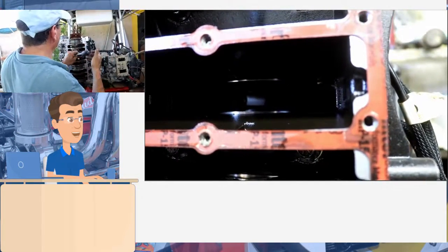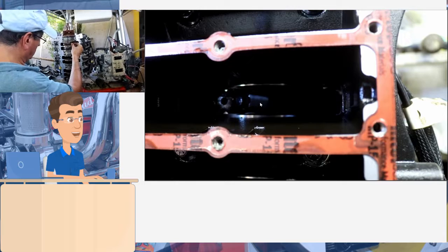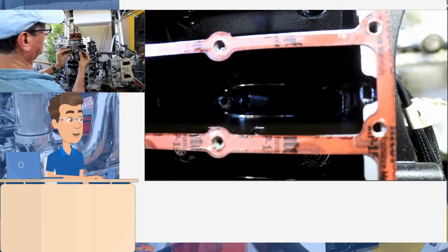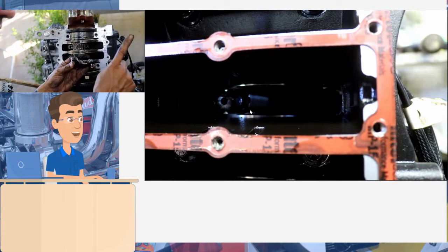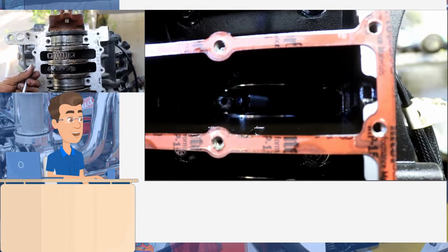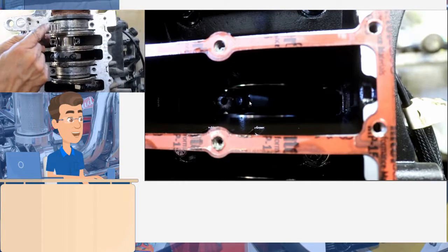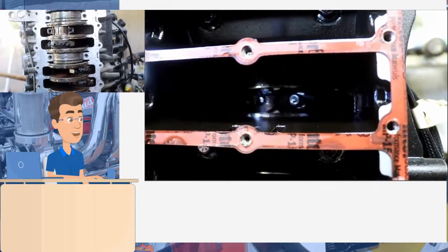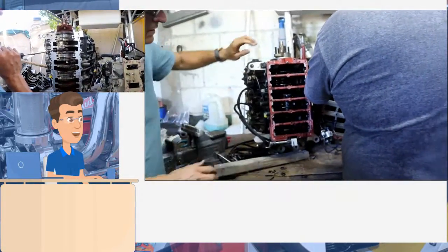Yes, my friends, those connecting rods have special bearings, the bearing that you have in the top left of your screen right now. Those bearings are not plain bearings, they are needle bearings. Exactly. And we are going to study those bearings later. Those bearings receive the oil here in the crankcase. The oil enters over there and lubricates those bearings. This is the crankcase, and the bearings are roller bearings or needle bearings.